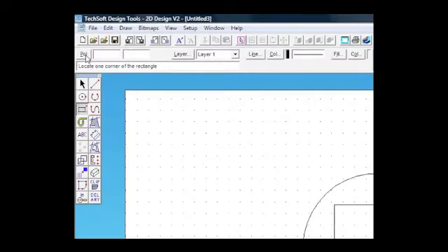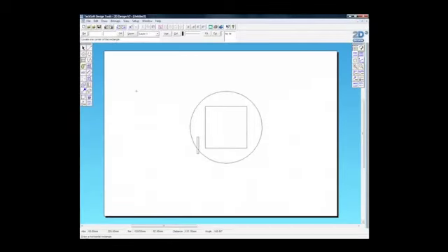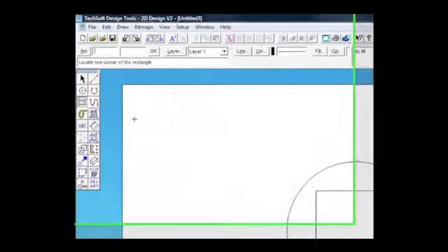Next, we're going to make the slots for the joints. In abs again, we want 167.5 by 142.5. Click OK. Click the abs button onto rel again, and we're going to define the size. And there we have one of our slots.